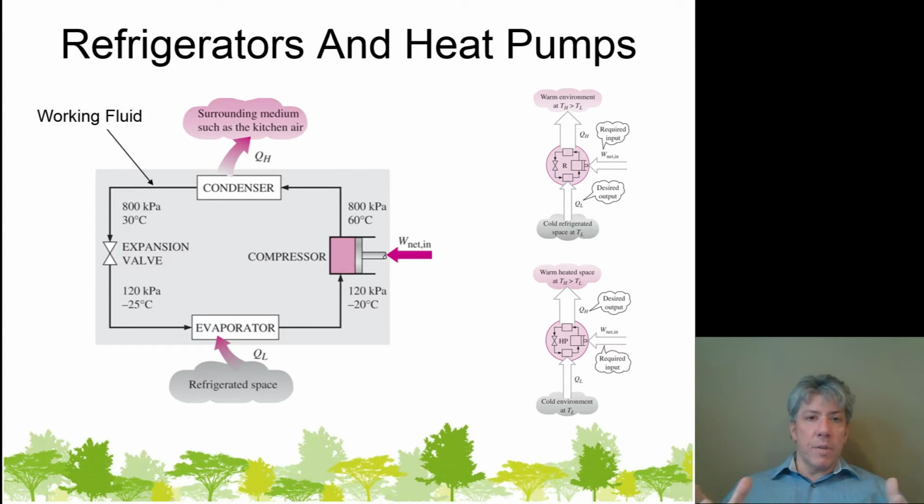Now, common features of refrigerators and heat pumps, just like heat engines, they use a working fluid, although they use something different. Technically, the working fluid in your car's engine is air. The working fluid in a lot of refrigerators is R22. Sometimes it might be R134A in your car. My house, I went to 410A, I believe it is, for my heat pump. It's just different refrigerants. I don't use air for it.